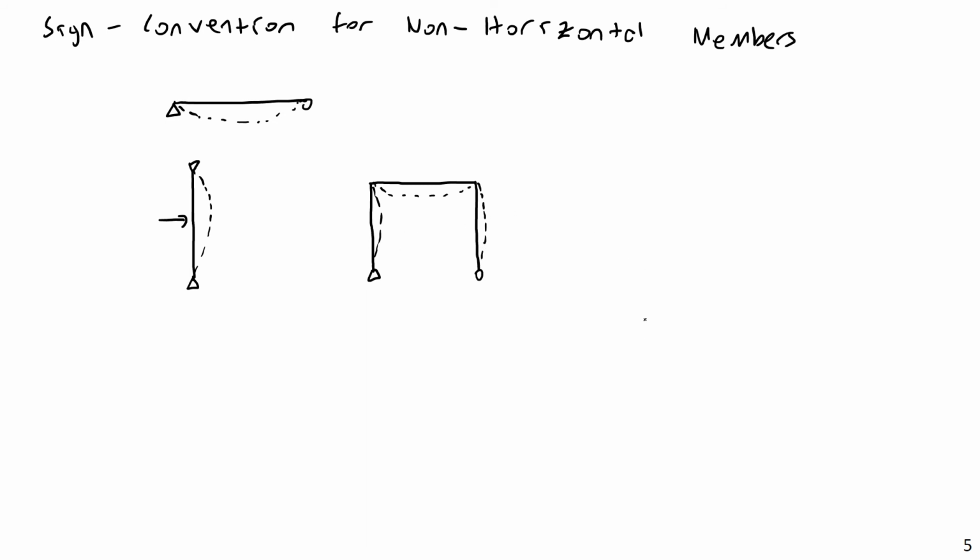Well, at that point, our basic, simple definition of positive and negative bending does break down a bit. One common thing you can do if you have a really complex frame is just say that all bending downward or to the right is positive. That's one simple way.